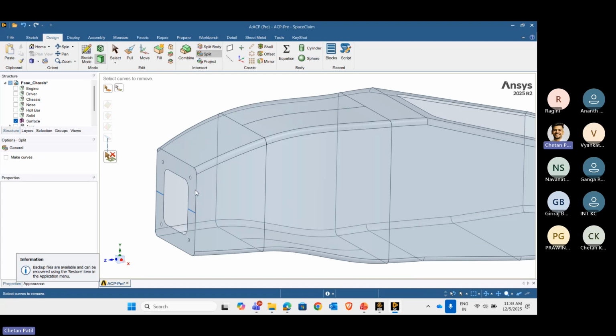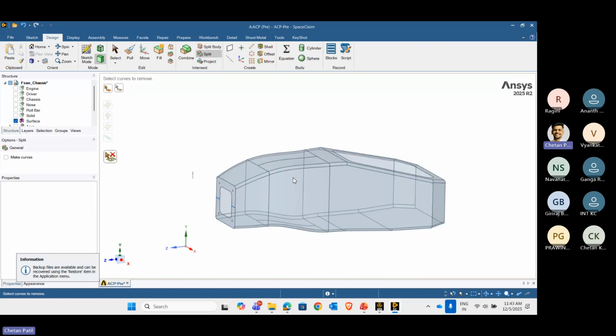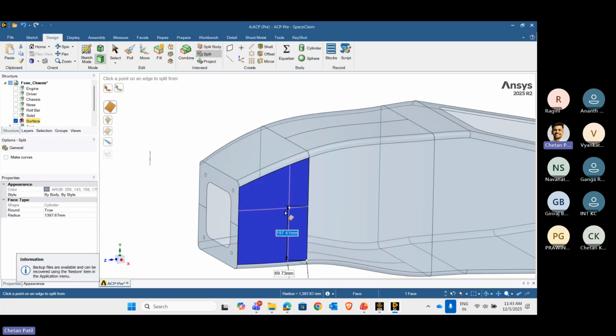Now, after this, I want to do the same kind of modification on the sides of the geometry. So I'll select this particular surface over here. I can't divide this into half by just clicking on the tool present over here, that is the UV cutter point. This tool is only used whenever there is a symmetric surface, where both the sides of the face are of similar sizes.